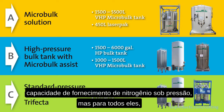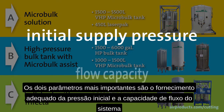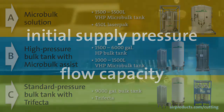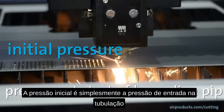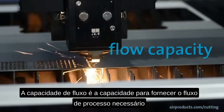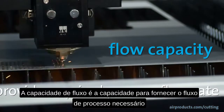But for all of them, the two most important parameters are the initial supply pressure and the flow capacity of the system. The initial pressure is just that. It is the pressure at the start of the house line piping. The flow capacity is the ability of the system to provide the required process flow rate.